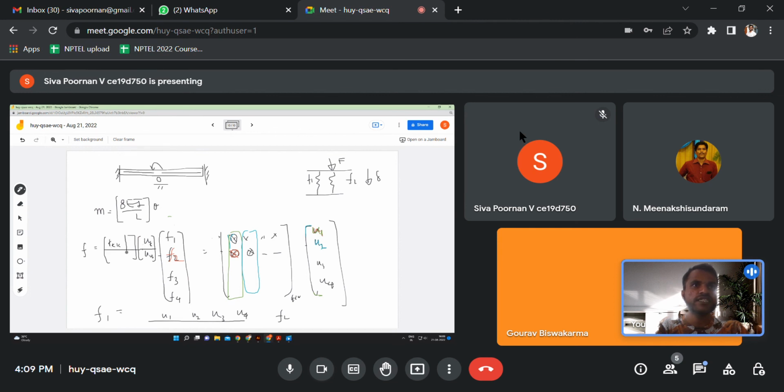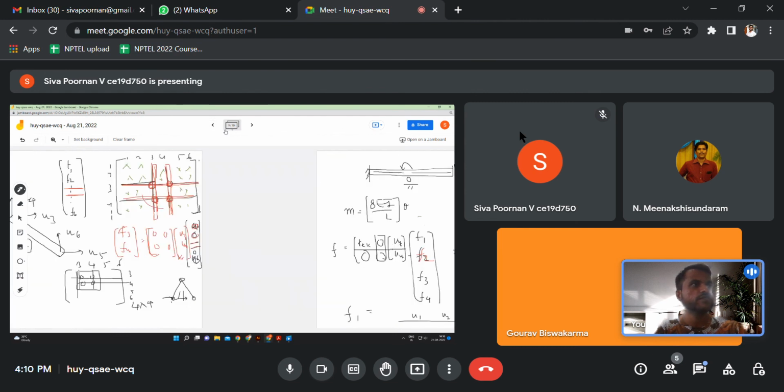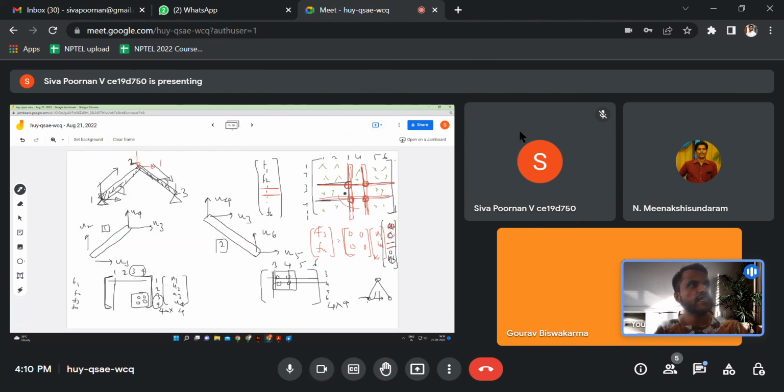You cut it, and then you are able to split it into 4 different sub matrices for the stiffness matrix, and then you say that you are able to take only one sub matrix of that. That's what we saw here. So it doesn't matter where the sub matrix is appearing. In our case, it appeared to be at the center. It could also be appearing in one corner.